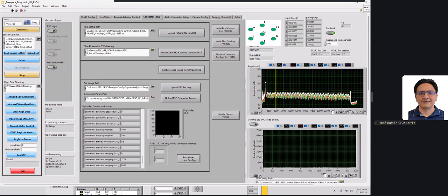One more thing that I'd like to run through, especially when you bring up a new free space connector: we got lucky here in that the connector location, so all the optical components that you have here, all have more or less a similar length, such that our peak finding algorithm was able to latch onto this guy. But sometimes when you have a hex pack that's slightly longer, slightly shorter, or something like that, it actually creates enough of a path length difference such that our registration can't line up. So I'd like to run us through the process of actually doing a connector locations find manually.